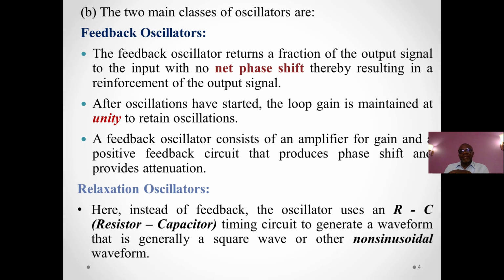When we say no net phase shift, it means that there is no reversal of phase, that it is exactly the signal that comes out of the output that is fed back, that the phase is the same, must remain the same for it to aid the input and improve the next output.